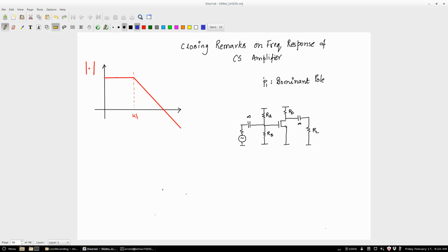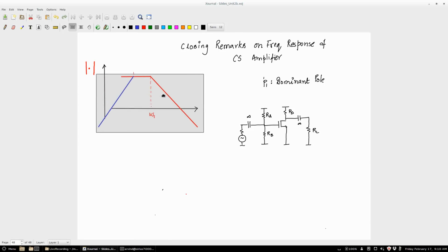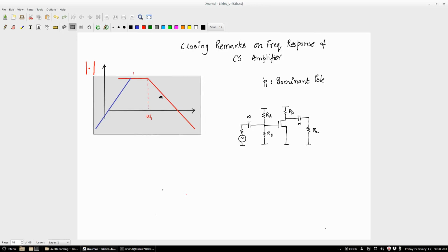Right. So, we did not consider that aspect. So, if you include the coupling capacitor, effectively you will have a response that rolls off at low frequencies. Again, it's just a single order, so it should also go at the same 20 dB, right? Does that make sense to everybody? If you don't, please ask. If it doesn't, please ask. Okay, does that look the same slope?